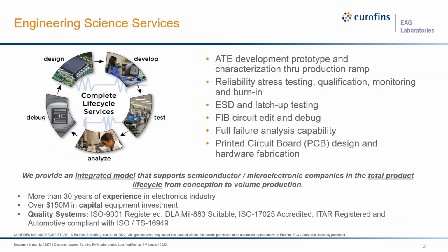So the Engineering Sciences involves quite a number of analytical tools that we can use. We have ATE to basically go and check your devices or your wafers and see that they're working properly. We can do reliability stress testing, qualification, burn-in, ESD and latch-up testing. Of course, the Circuit Edit FIB, and then we have a full failure analysis capability as well. We also have a PCB or printed circuit board group that helps design hardware for those tests or for the ATE applications.